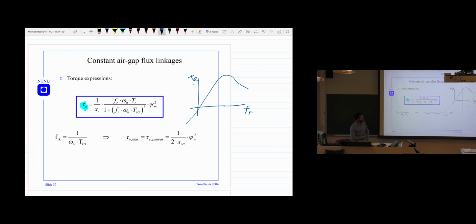So you'll see similar characteristics as the previous one. The one thing is that here we see that when we increase the loading and you want to keep the magnetic flux constant, then the rotor flux reduces and the stator flux increases for this condition. Therefore, we don't use this one that much, but it gives something like this. Any question here?